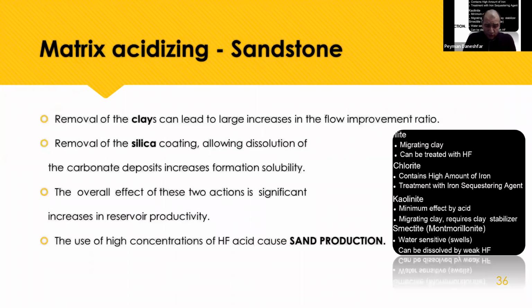In sandstone formations, acidizing is good. We open or remove some pore plugs in the porous spaces. But the acid may dissolve more elements, more sand or silica or clay or anything.